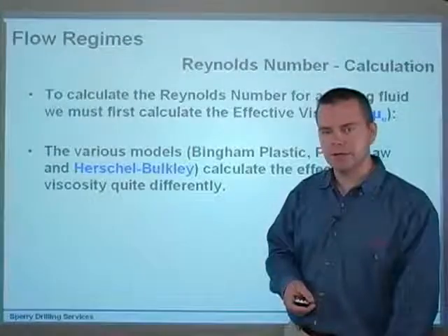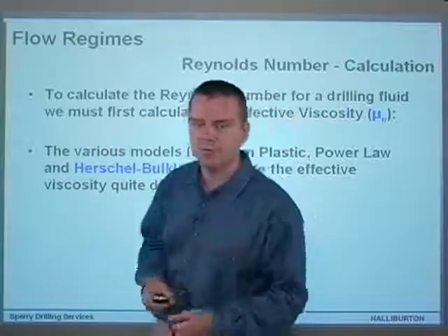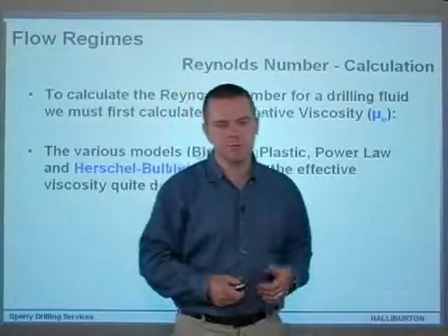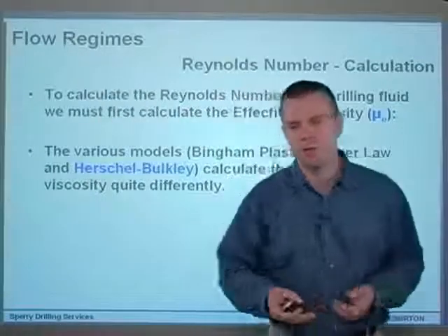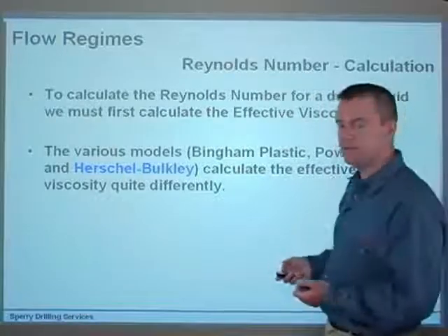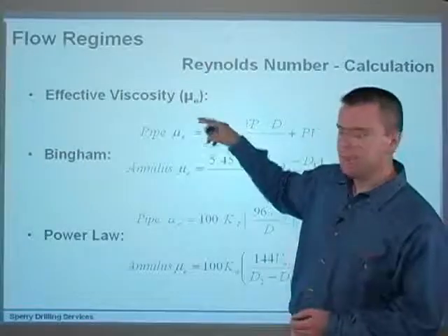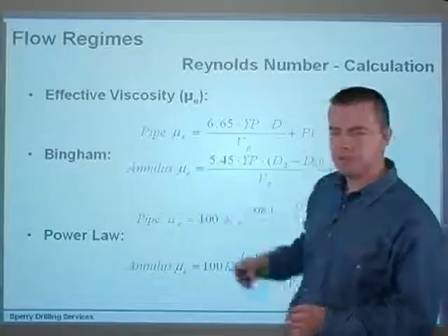To calculate the Reynolds number for a drilling fluid, we must first calculate what's called the effective viscosity. The various models, Bingham Plastic, Power Law, and Herschel-Bulkley, calculate the effective viscosity quite differently. Okay, taking the effective viscosity, which is mu sub E here, for Bingham and Power Law, just as an example.